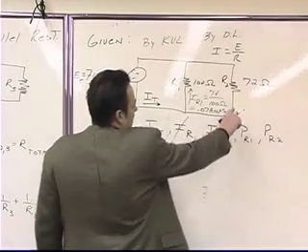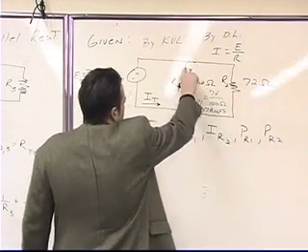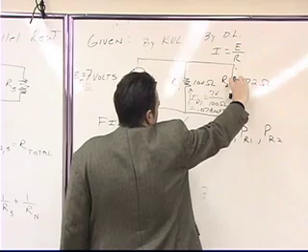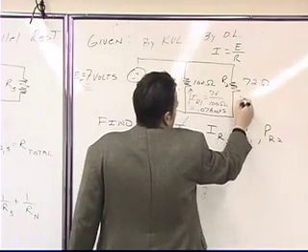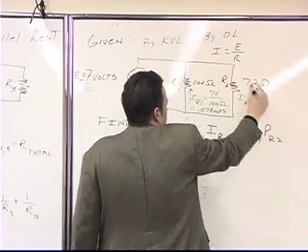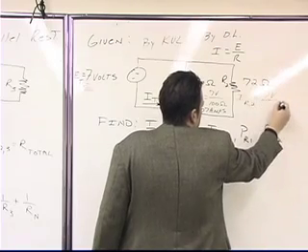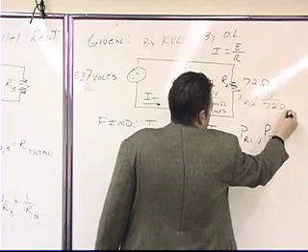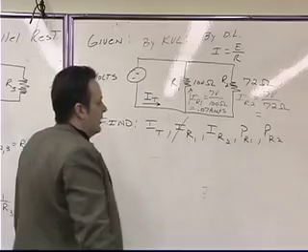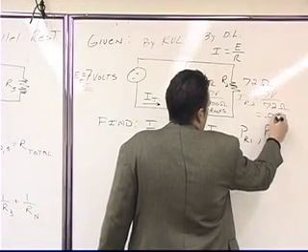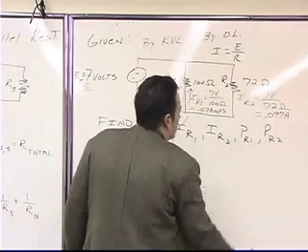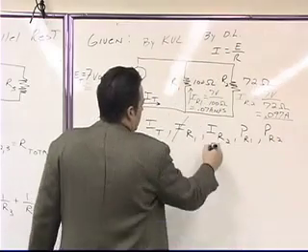Likewise, I can do the same thing here. If I know that this is a closed loop and that this has 7 volts across it, then this has to have 7 volts across it. So the current that's flowing in resistor number 2 has got to be equal to the voltage across the resistor, which is 7 volts, divided by the resistance, which is 72 ohms. So what does that come out to? 0.097 amps. So I've just figured out that guy.